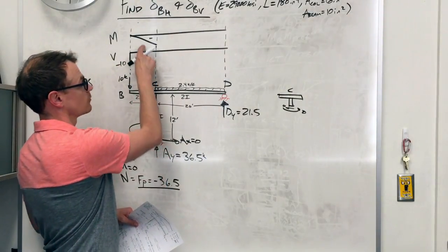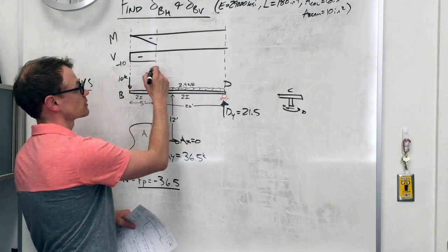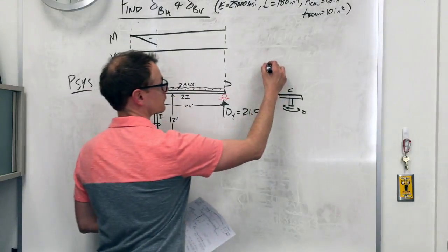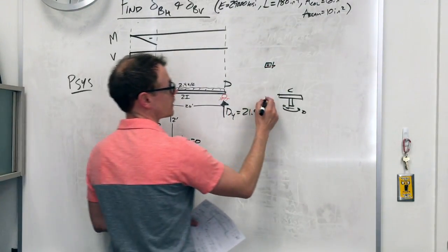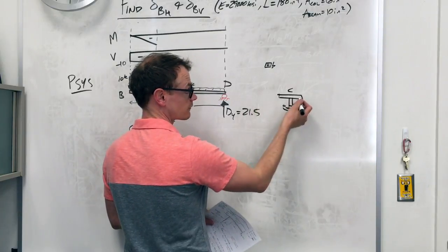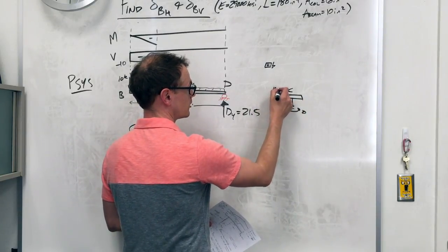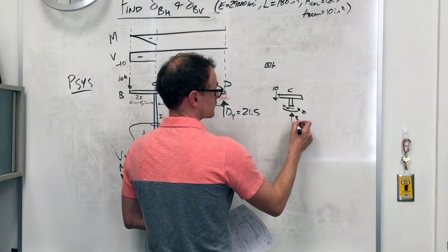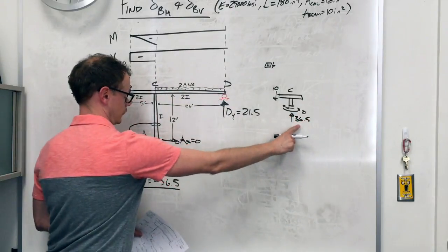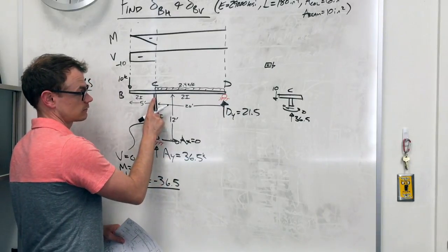I have shear and moment here. This is negative shear. That means plus goes like this, right? Negative shear on this side means it goes up. If I transfer to the other side of the cut, it means it goes down. So I have 10. Here I have 36. Right, this comes from the AY, 36 here.